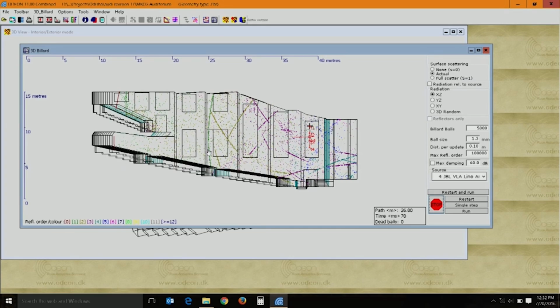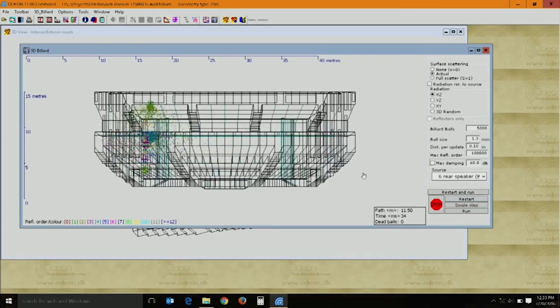which means you need an amplification system. If it is going beyond certain milliseconds, that is where a deciding point happens, on how many sets of speakers and how to design the amplification system itself. Say for the line array speaker, we have a specific set of speakers to cater; the lowermost would probably cater to this zone, the next might cater to this zone, then here, then one for the balcony. We have certain amplification sources behind the balcony also. This is a rear speaker. This is how the sound propagation happens.